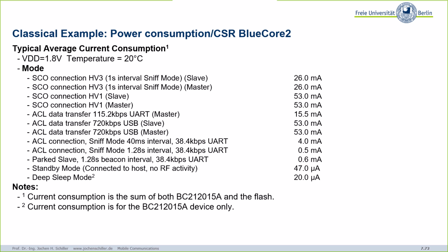So this is why I gave you from this old chip where we measured this, the sniff modes really save a lot of power. You see, there's a big difference. So less active, but also if you look at this example, you see both versions have the same data rate, but one uses only 1/8 of the current, so power consumption really goes down.